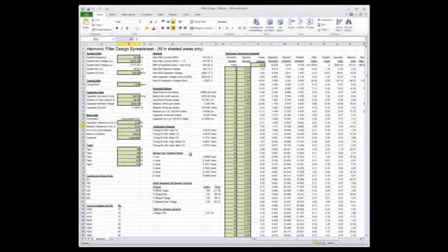One other thing that I put in here is called a blown can tuning check. So what I do is I see how my resonant point shifts when I blow 1, 2, or 3 cans. And what this allows me to do is determine, hey, if I have 2 blown cans, I'll simulate an unbalanced system and I'll see where the neutral offset is for an ungrounded Y bank. Thus, I can apply protection and determine a setting for it.